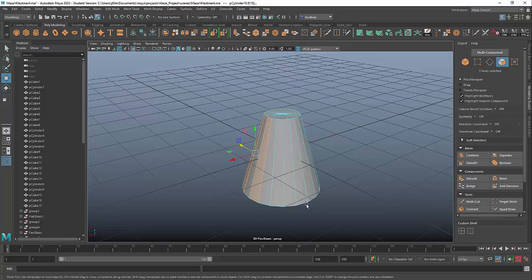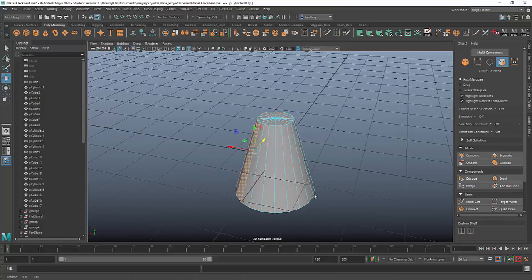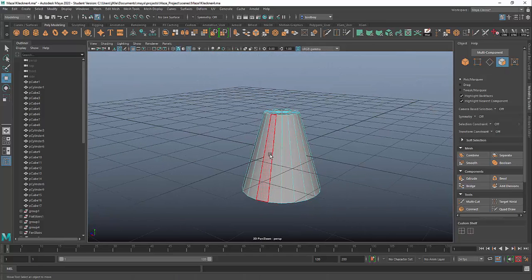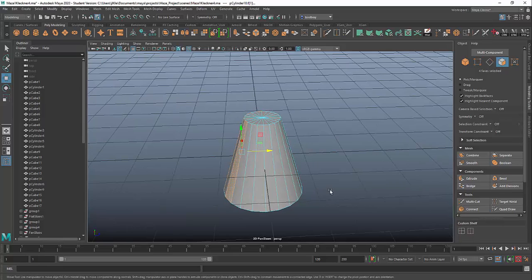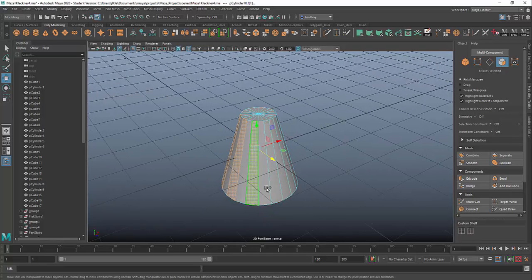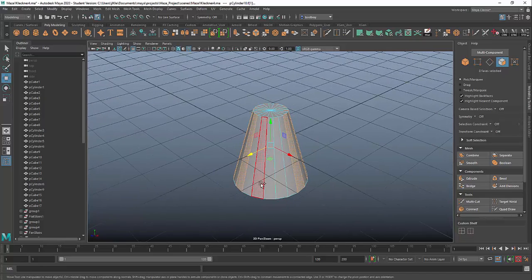So you want to make sure not to click off the objects with the left click without holding down the Shift. So I'm rotating it, and if I click out, see how it deselects everything? So just be aware of that as you do this. You have to make sure that you're just rotating and then holding down Shift. It's a little tricky in the beginning to do something like this, so don't freak out. Take your time, try and do it.